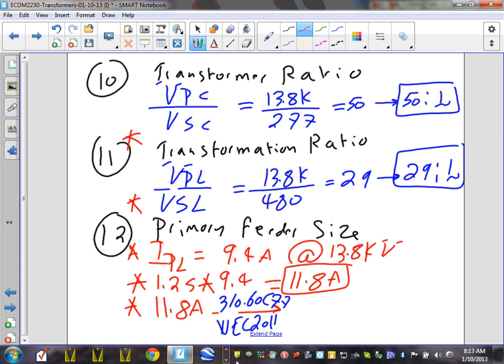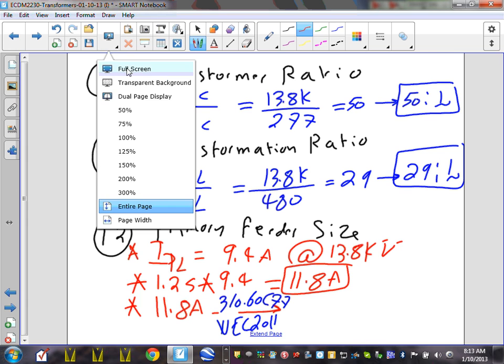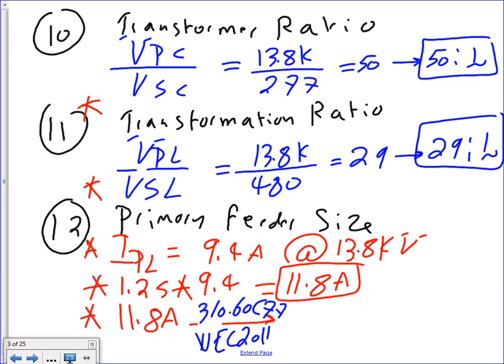So now let's go back and get our number 6 here. How many conductors though? How are we going to write this one? This will be 3 conductors. Why 3 conductors? 3 phase. Do I need a neutral in the primary? No neutral. 3 conductors, number 6 AWG, and what's the insulation? MV-90. Okay. Did they do it right? We use the 90, right? Yeah, default is 90.